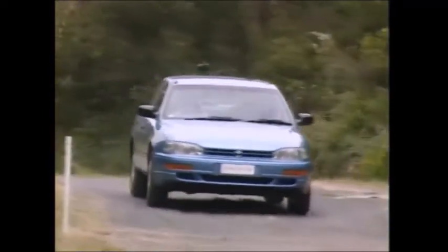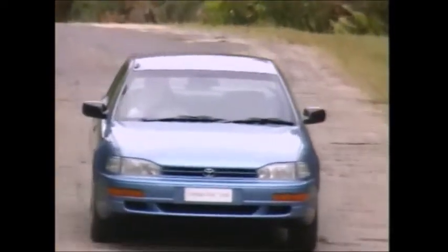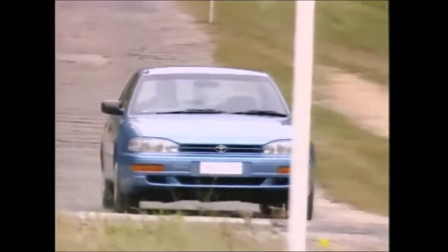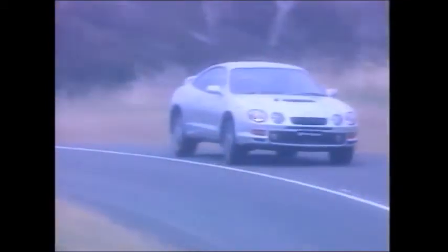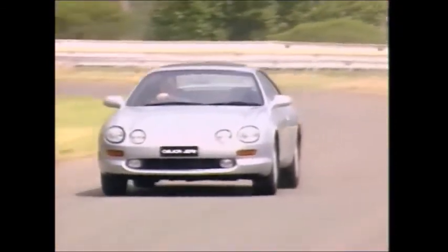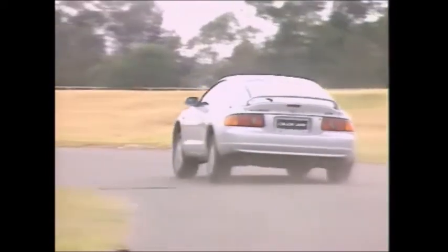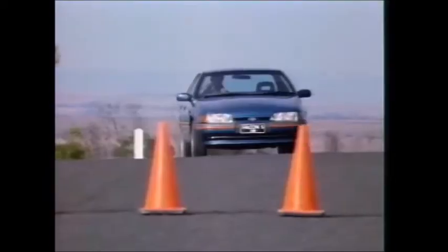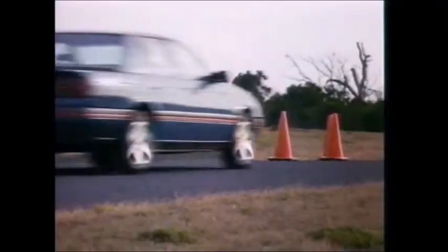Every vehicle has static weight distribution, whether it is at rest or travelling in a straight line at a steady speed. This is changed laterally by centrifugal force when the vehicle is turning, and in a fore and aft direction during acceleration or braking. During cornering, centrifugal force puts more weight on the outside wheels. Acceleration puts more weight on the rear wheels. Deceleration or braking has the opposite effect.